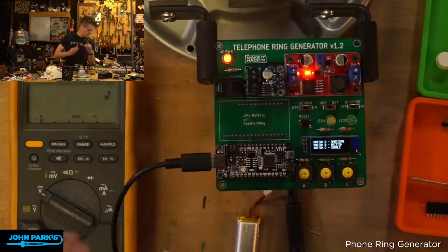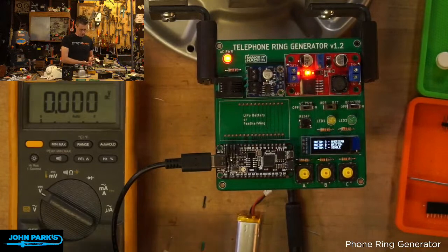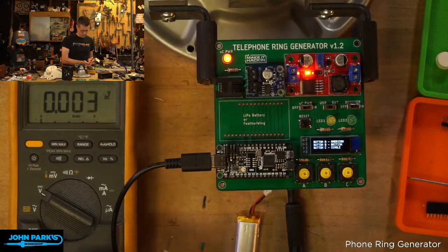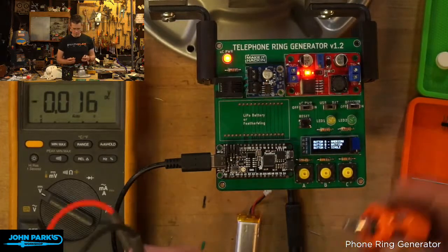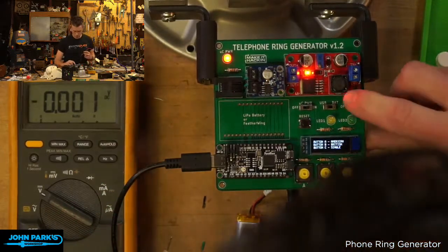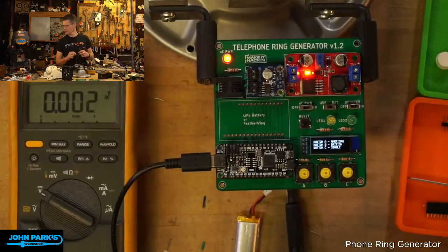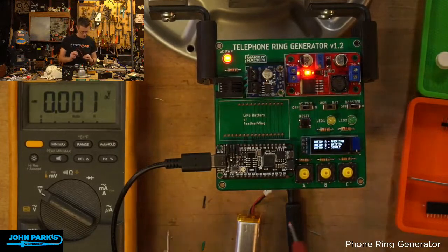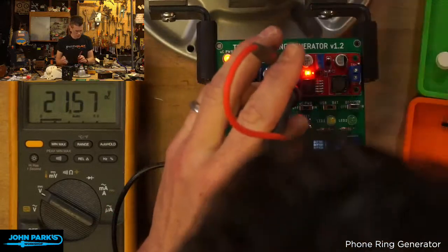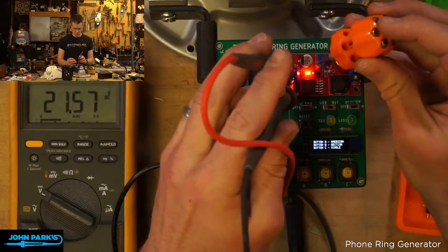So I'm going to grab a little flathead for this trim pot. Did I say that? Oh, I already have one on here. Okay. So there's a little trim pot right here. Turn the booster switch on. Okay, yep, we're on. Thank you, Andy Calloway. Saw my meter was set to AC. It's a fun mistake.